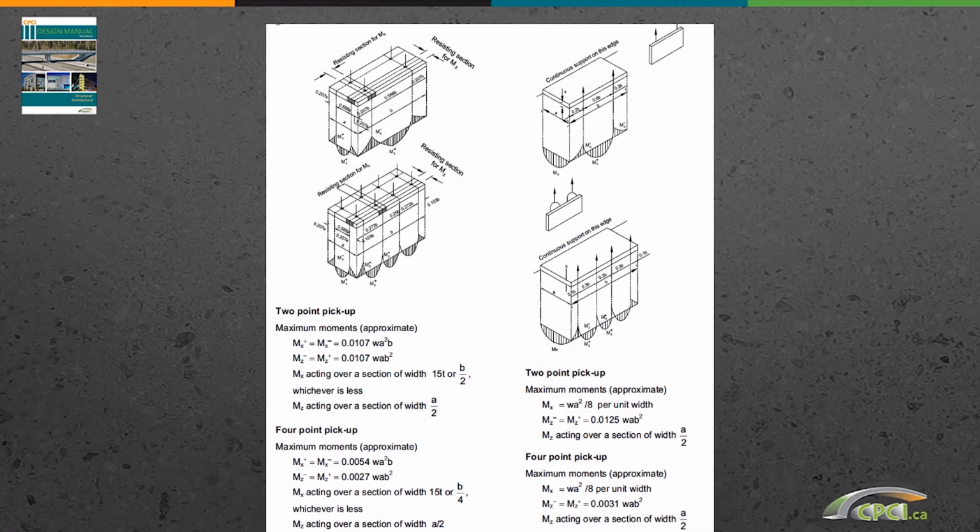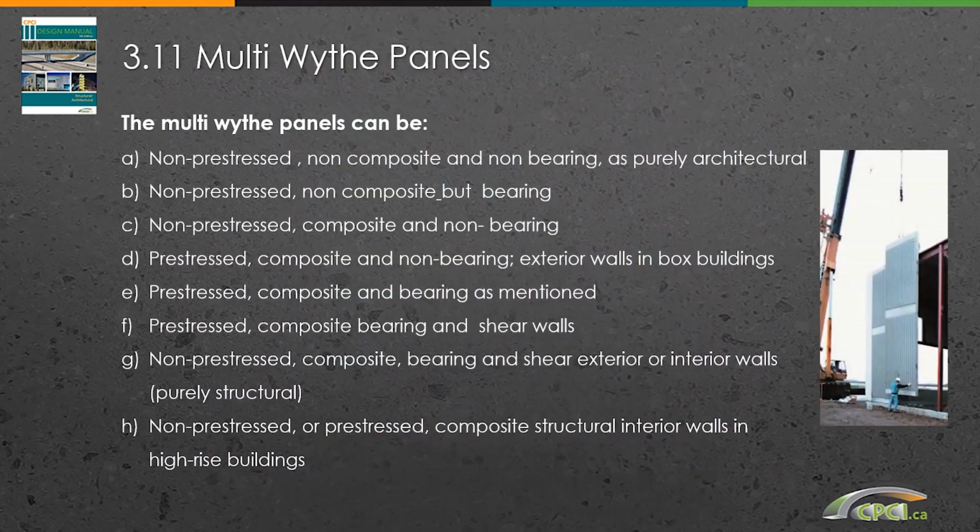This is a standard location for picking points, depending on whether the section is prismatic or not. If it's not prismatic and has holes in it, or has doors, or has certain different section thickness, then we end up with a problem, because we need to make sure that these points essentially coincide with the CG of the element. So we need to calculate the CG in these cases, not just use this formula.